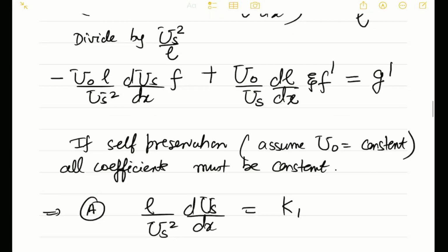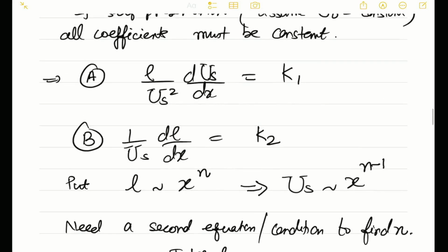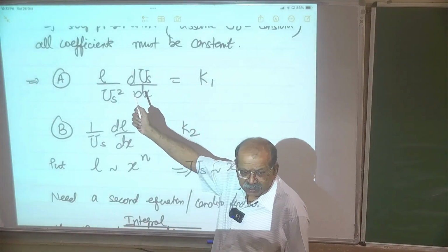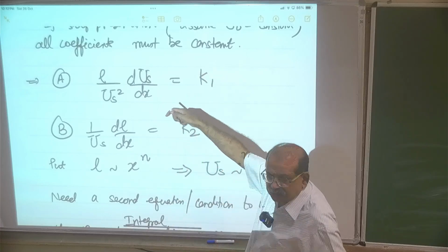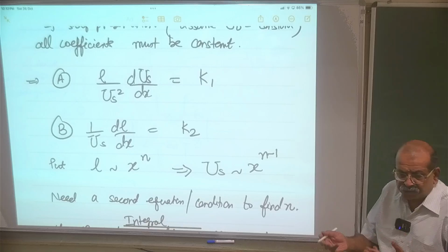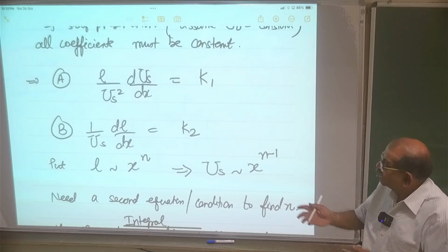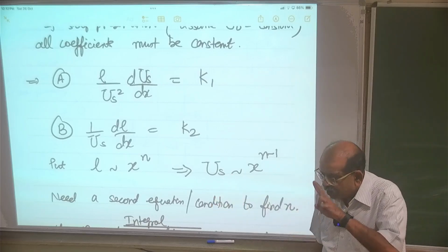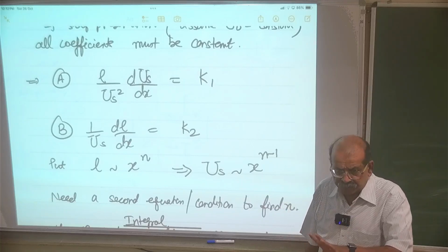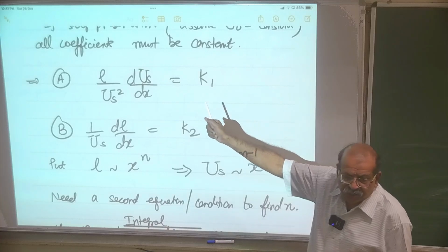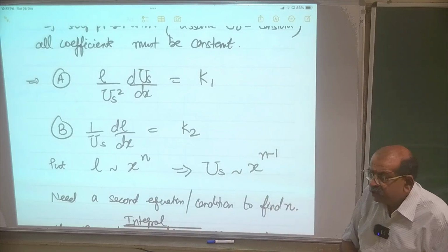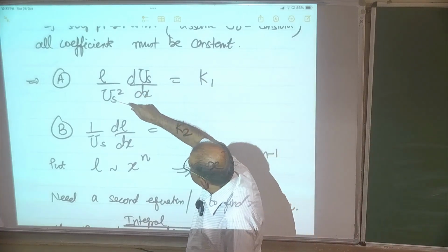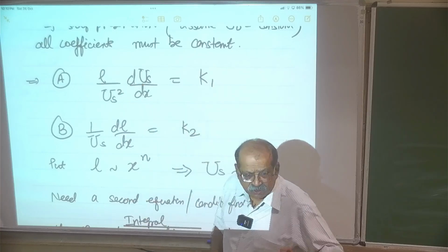That is the equation, and then we derived the condition under which we will have self-similarity. We wrote everything in terms of f of a non-dimensional variable zeta, and all y's were eliminated. So there were only two variables in the equation, zeta and x. Wherever functions of x came, we said they should be constant. Only then will we get this self-similar solution. So we got two conditions. There were two quantities, us and L, which depended on x.